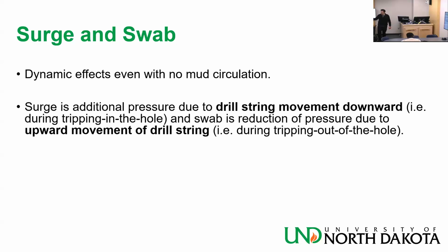Now, modern day rigs have the capability of balancing that a little bit, and you are able to trip in the hole and out of the hole faster. They like that because tripping out of the hole takes over a shift, like 12 hours or something.